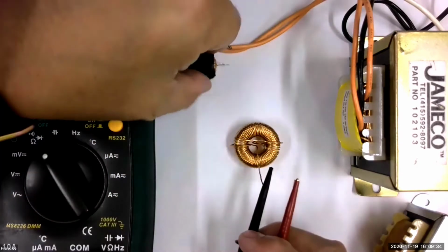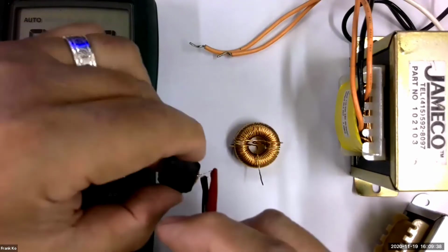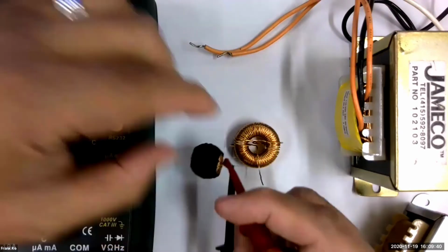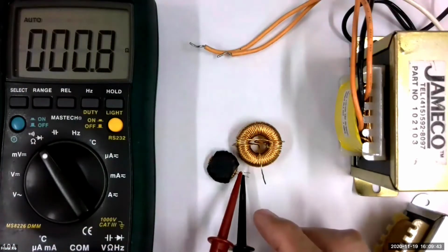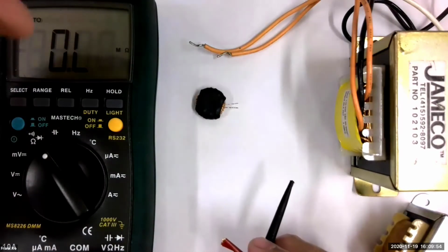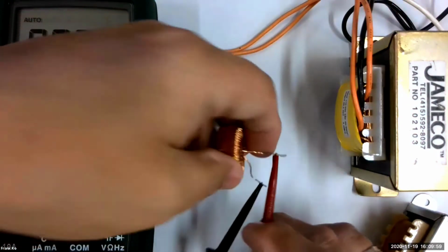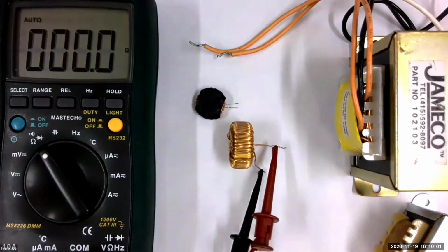And if I go to measure another one of these using DC, right here, 0.8. The LCR meter, yeah, one of those. I'm going to measure the inductance. And here's the bigger coil, and we go like so. Measure this one, it might have a few more ohms, possibly. There's a lot of wire there. Yeah, it's still 0.1, 0.2 ohms, not a whole lot of ohms.